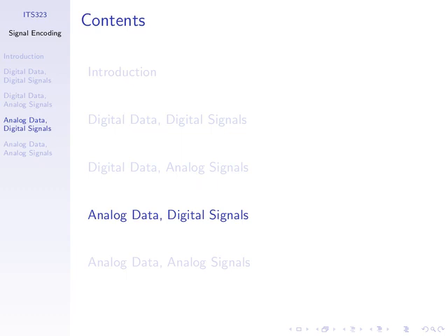Why? Because at this frequency, 670 megahertz, we can transmit over different distances. The antennas we need to transmit are much smaller. Generally, the lower the frequency, the larger the antenna. If I want to transmit low frequency signals, I need a very big antenna. I cannot fit a very big antenna in my pocket. So by shifting up to 670 megahertz, I can have a small antenna and transmit to the wireless receiver. It can pass through obstacles differently. So this is the portion of the spectrum allocated in Thailand to wireless microphones. I'm allowed to transmit at this frequency. In fact, on the back of this device, it has some approval by the National Telecommunications Commission, some class device which says it's allowed to be used in Thailand at this frequency.